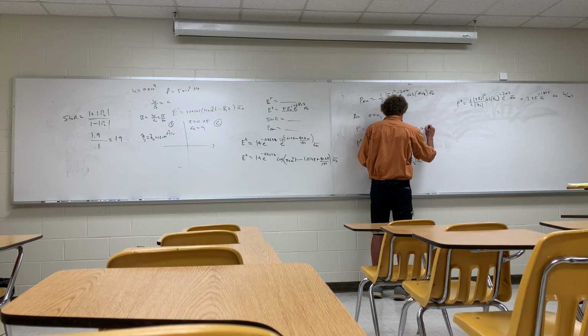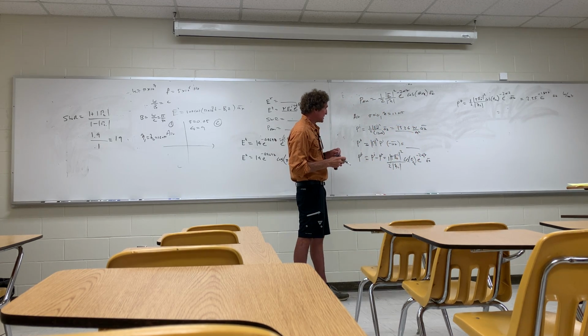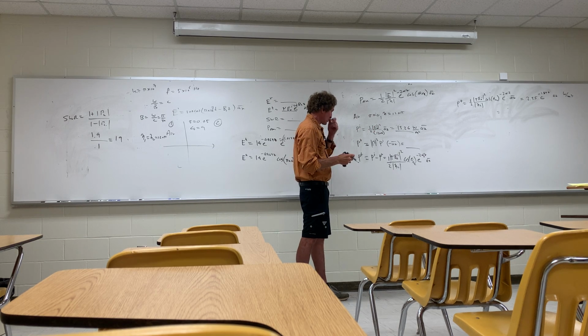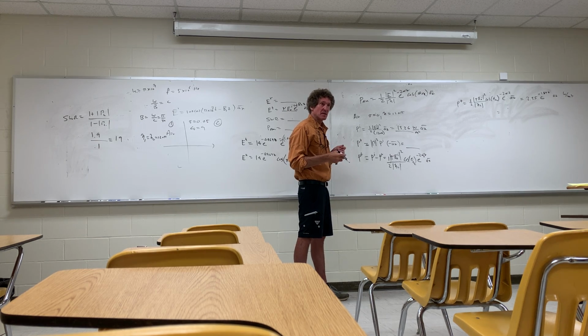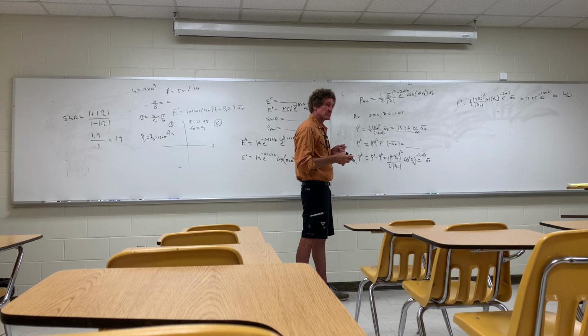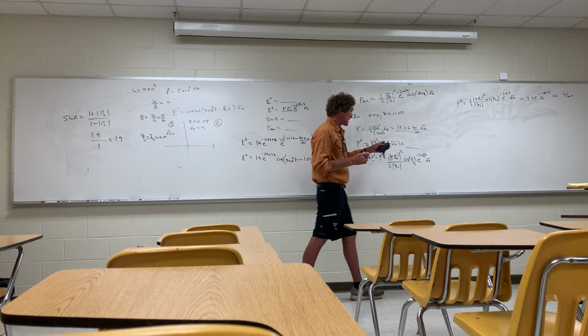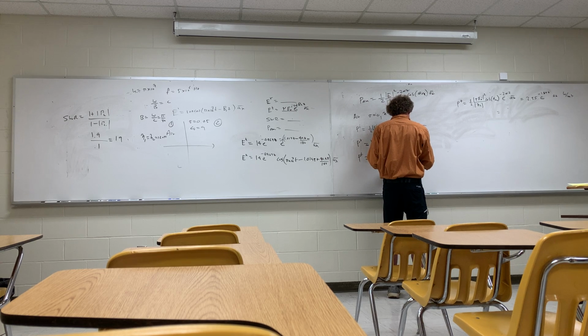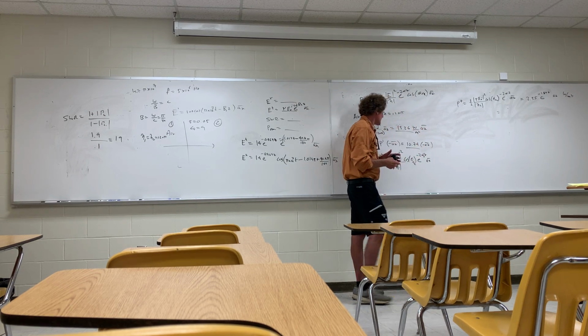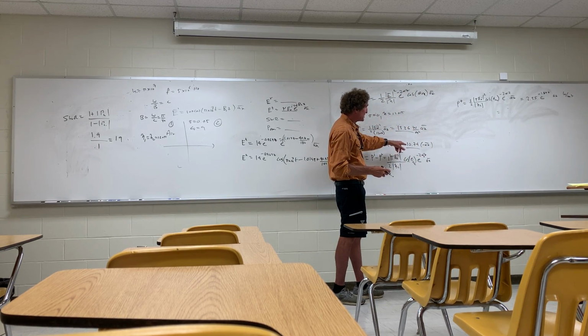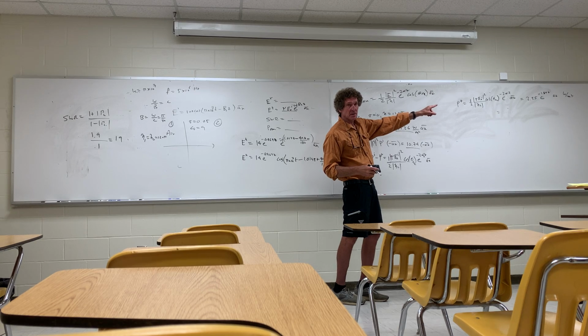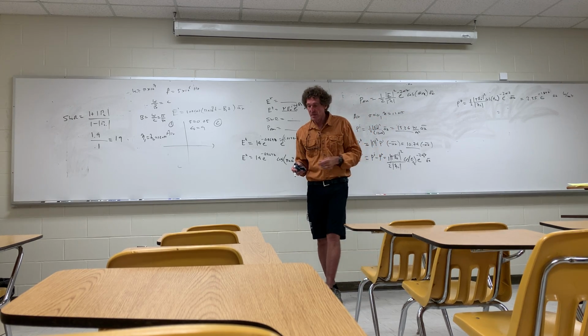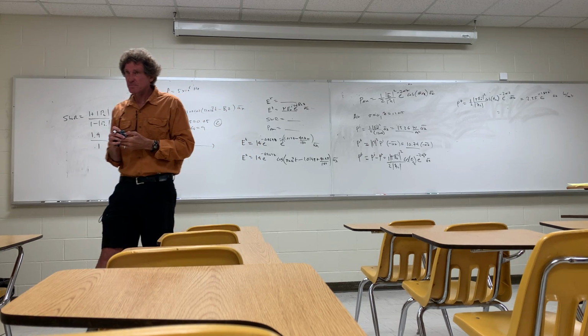All right, in the AZ direction. What does this come out? Just take gamma and square it, multiply it by that. Gamma is 0.89, is that the reflection coefficient? 10.74. That's what I'm getting. And it's got a minus AZ, it's propagating the other direction. If you take 13.26 minus 10.74, what do you get? 2.56, about that. I know there's probably some round off errors, but that's how you get it.